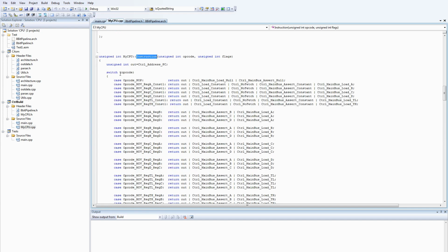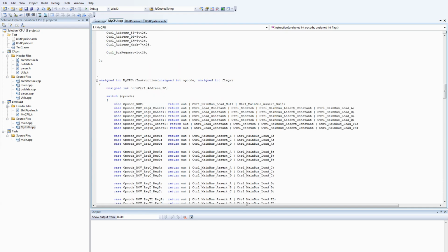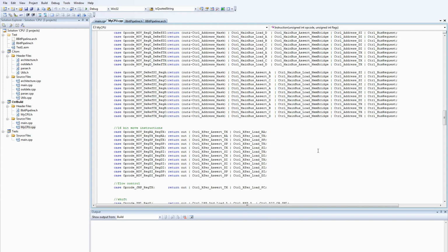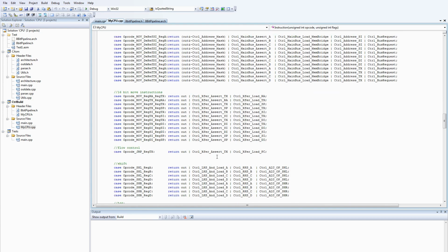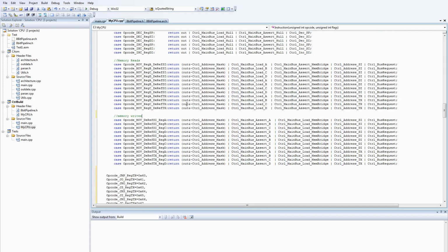So in here I've got a large switch statement, so I can do a case and then the name of an instruction taken from that previous header file, and then I can basically return a value which is setting whichever control lines I want at whatever pipeline stage I want. And then the wrapping code will iterate over that through all the possible permutations, and save it out as 4 different files for the 4 control ROMs, and this gives me a really quite neat way of going through and generating those ROMs. Keep the comments up to date.